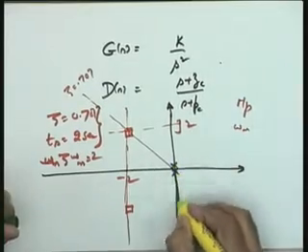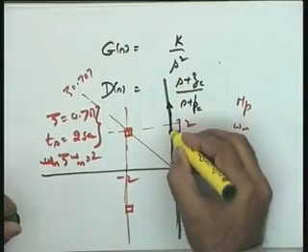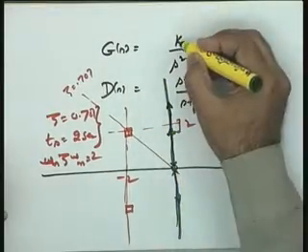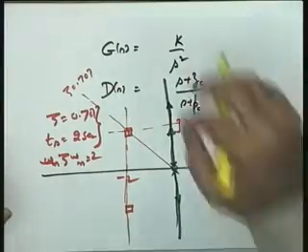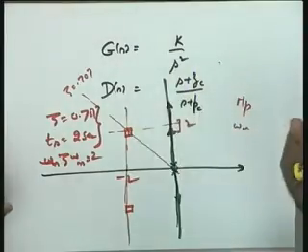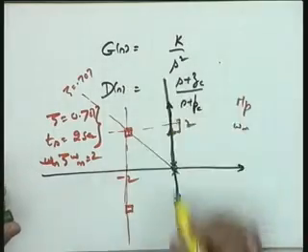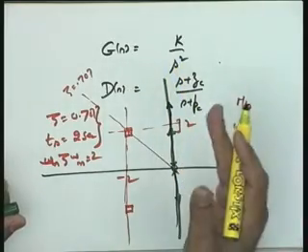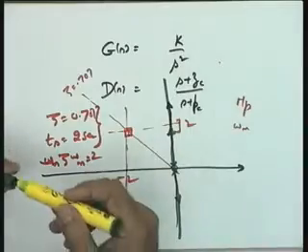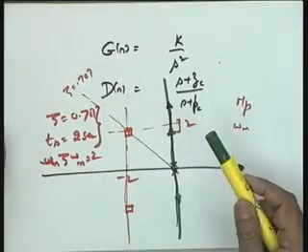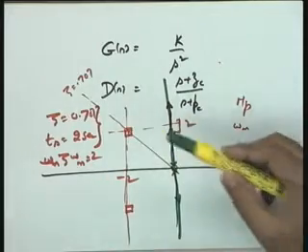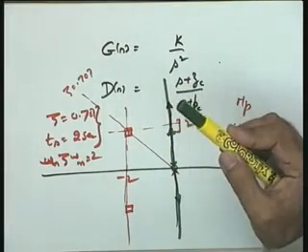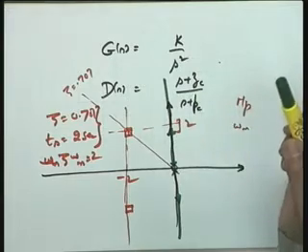Now you know your root locus plot of an uncompensated system. Note the word uncompensated. The gain k, which is an adjustable parameter, has been shifted to the uncompensated system, though you may realize this value of k using the compensator only. So you find that this green curve represents the root locus plot of the uncompensated system. The requirement is to pull it on this particular side so that the root locus plot passes through this particular point. If it does, it means your requirement of the transient accuracy will be satisfied.